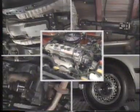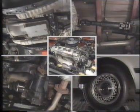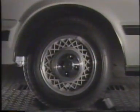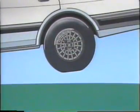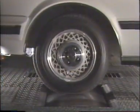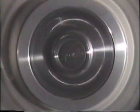A vehicle has a number of components that can be vibrating forces. We will show you some of them now. When a car is parked in the same place for many days or weeks, there will be a flat spot at the bottom of the tire. This flat spot will cause the wheel to vibrate each time the tire turns. This can, in turn, cause the body of the vehicle to shake.